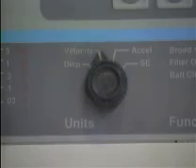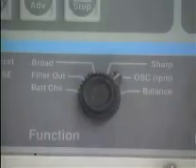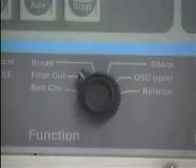However, the actual choice may be based on the company's vibration monitoring program or on the speed of the machine being tested. After the vibration characteristic has been chosen, the frequency filter switch setting is selected. Usually, a vibration measurement is begun by taking an overall reading.